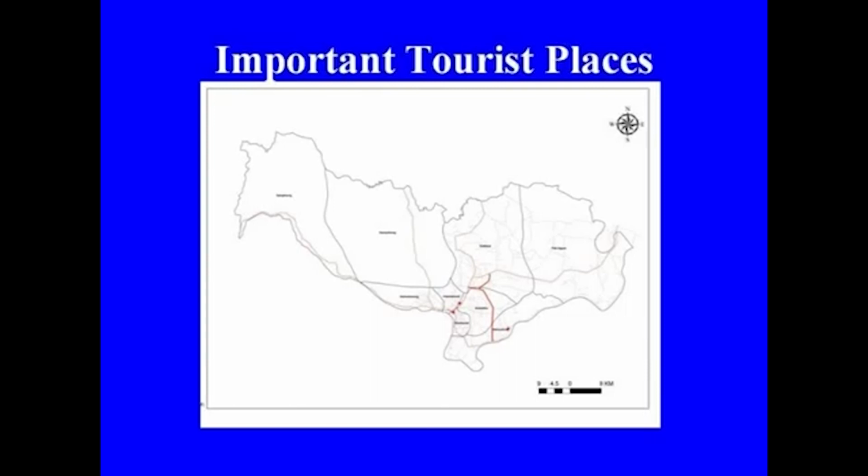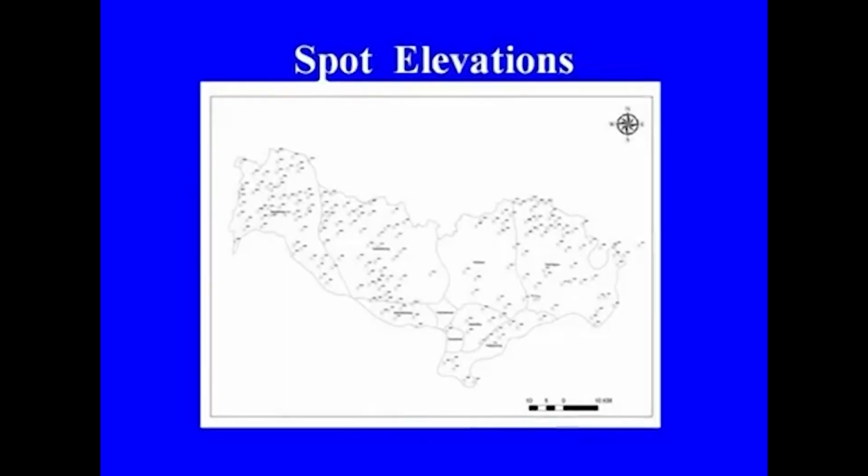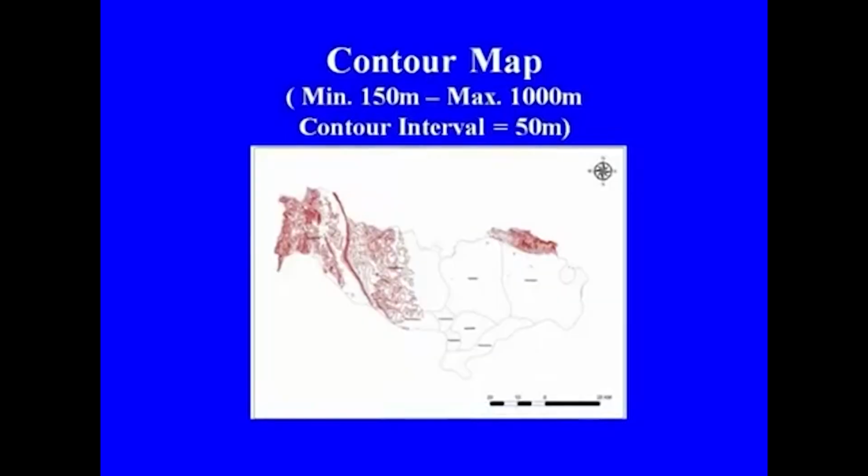Ground information plays a very major role. So, information related to the ground was made available from topographical maps. All spot elevations available were digitized and stored as point features. Subsequently, the contours also available on the topographic maps were digitized. The map information was available at a scale of 1:250,000, and thus a contour interval of 50 meters was available.